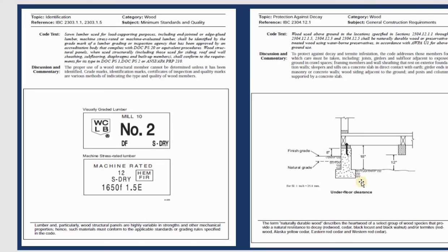If you go with the general contractor with the foundation, you need to remember the distance. This is the crawl space. It's 18 inches, and after that, if you have the floor joist under that or the blocks, you need to have 12 inches minimum so people can crawl under the floor and check everything like termites or something. Sometimes, every few years, you need to come in to check or clear up everything under the floor if you have the raised floor.